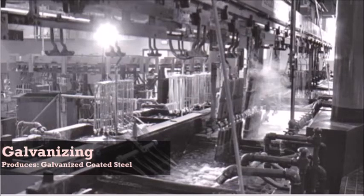Galvanizing is the process of coating iron and steel with zinc, which alloys with the surface of the base metal when immersing the metal in a bath of molten zinc, at a temperature of around 840 degrees Fahrenheit. Like other corrosion protection systems, galvanizing protects steel by acting as a barrier between steel and the atmosphere. However, zinc is a more electropositive metal in comparison to steel. This is a unique characteristic of galvanizing, which means that when a galvanized coating is damaged and steel is exposed to the atmosphere, zinc can continue to protect steel through galvanic corrosion.